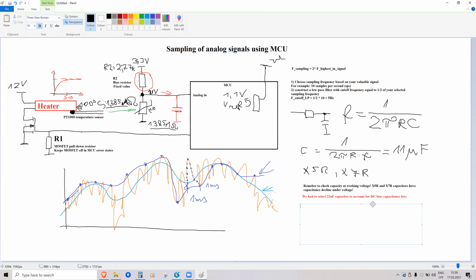And this will be the next layer. I'll just write it as 3. Use a software low pass filter, usually a simple average. So you would use a software low pass filter inside your microcontroller, which is usually done as just calculating the average. Some people use a rolling average, some people use something else.